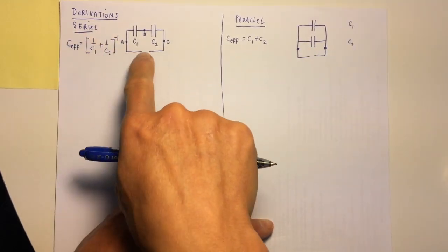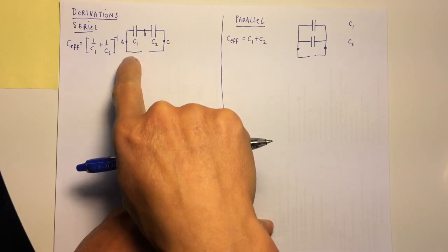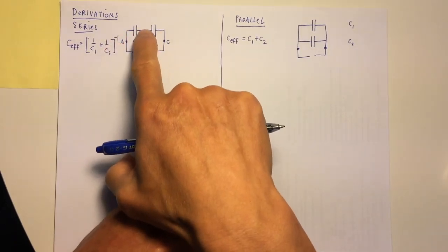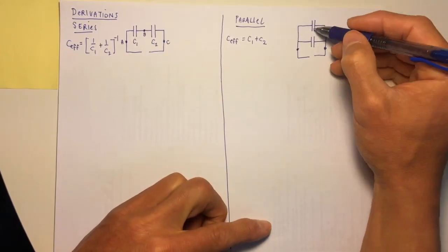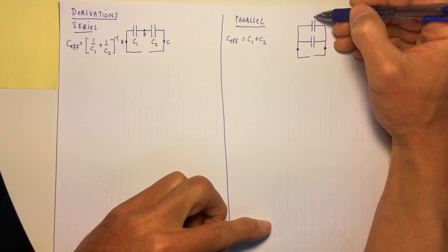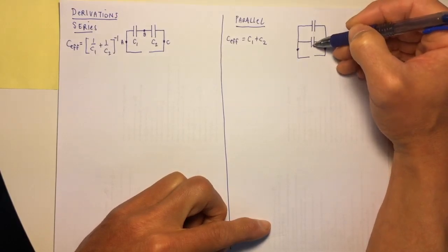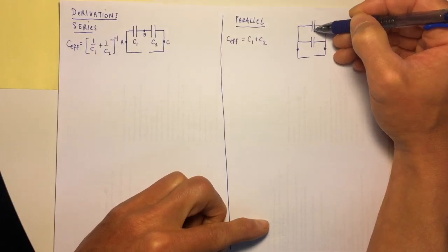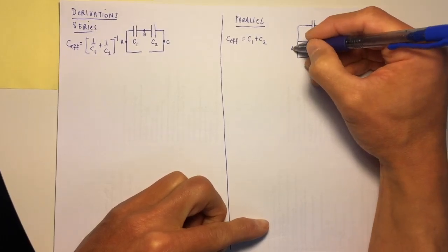In the series shape, I actually have 3 separate conductors: this piece of metal, the middle piece of metal, and the right side piece of metal. But over here, I can draw a clean line down through the middle of the capacitor gaps and the place where I'm going to insert a battery later. And this is just 2 pieces of metal, purely. So I've only got 2 conductors.